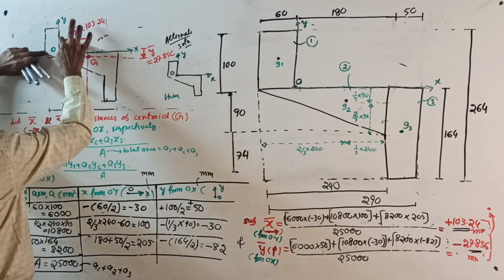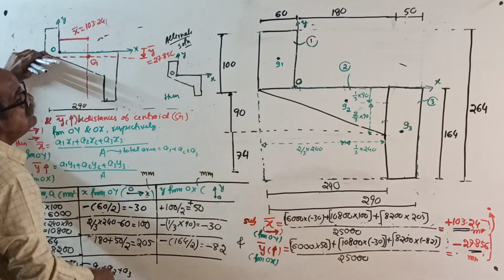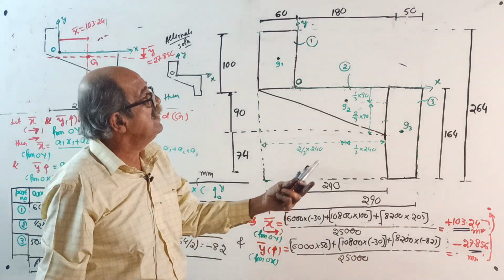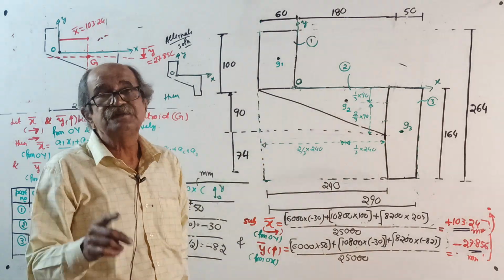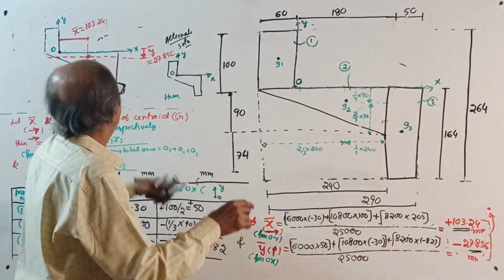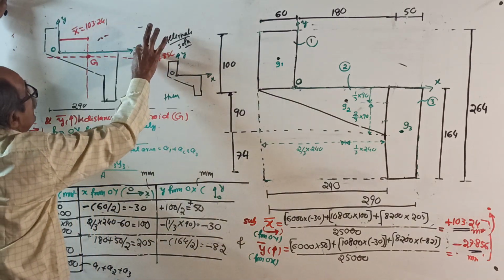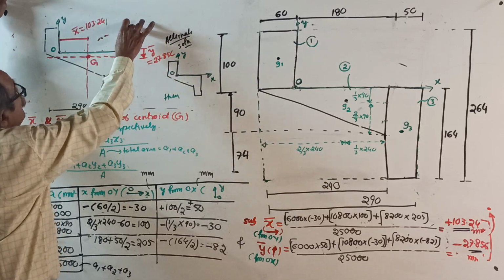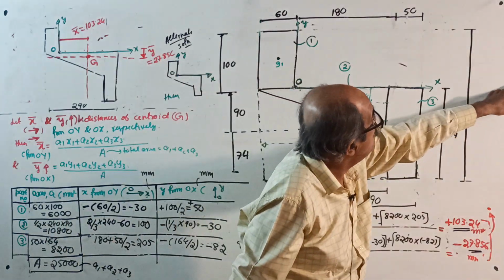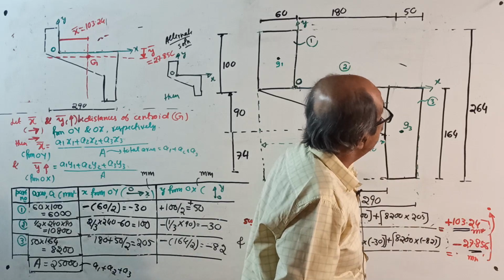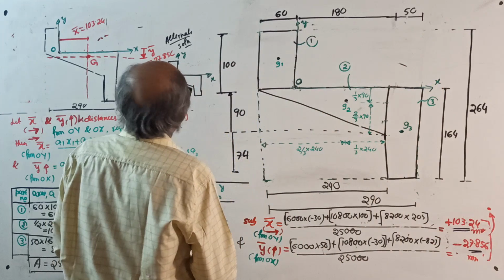Now observe correctly. This is 103.24. This is 60. That will give from here 163.24. That is the same as your earlier answer. Just because you change the reference, the centroid position will not change. And this is 100. This is 27.856. So from the top extreme, it will be 127.856. That was the last time's answer, 127.856. Somewhere I made a note, this is for the alternate solution.